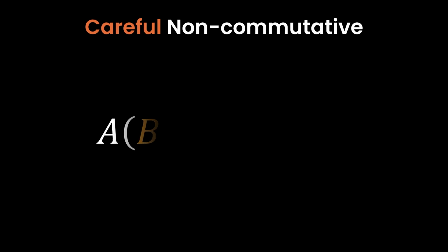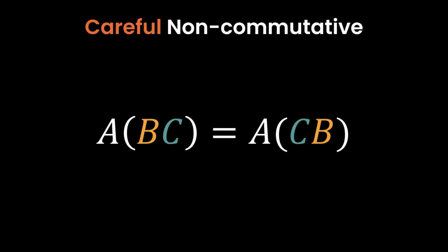One thing to be wary of is that the composition of homogeneous transforms is not commutative. That means that changing the order of multiplication doesn't give the same solution. An example of this is shown with these frame transformations. Translation, then rotation, doesn't yield the same end position as rotation and then translation.